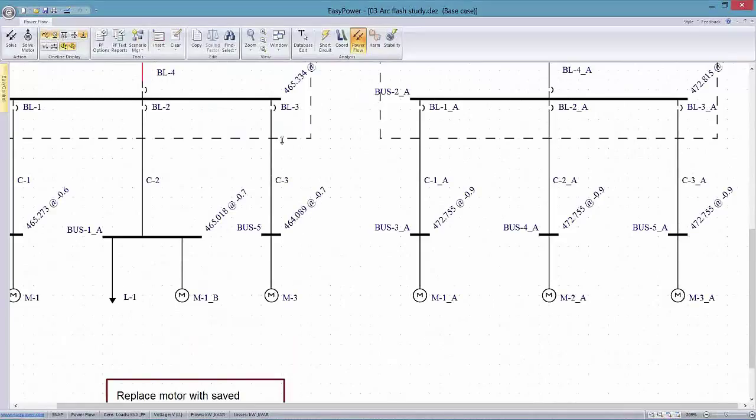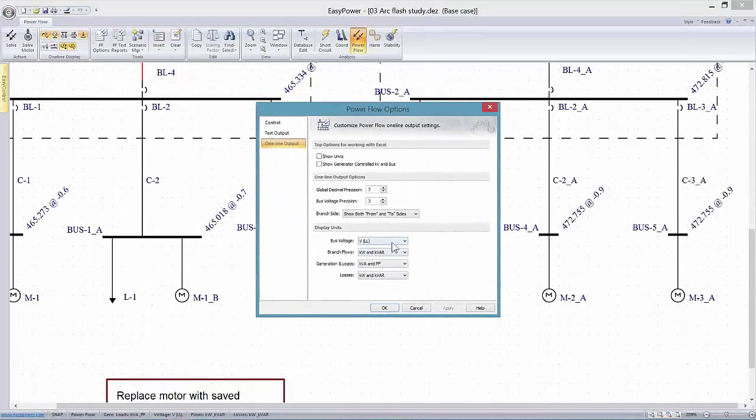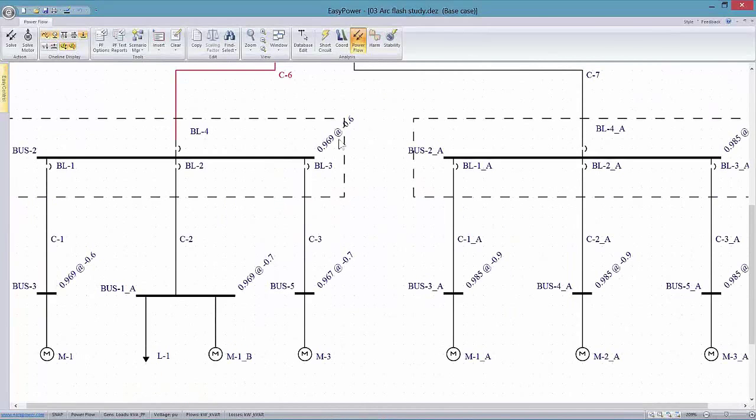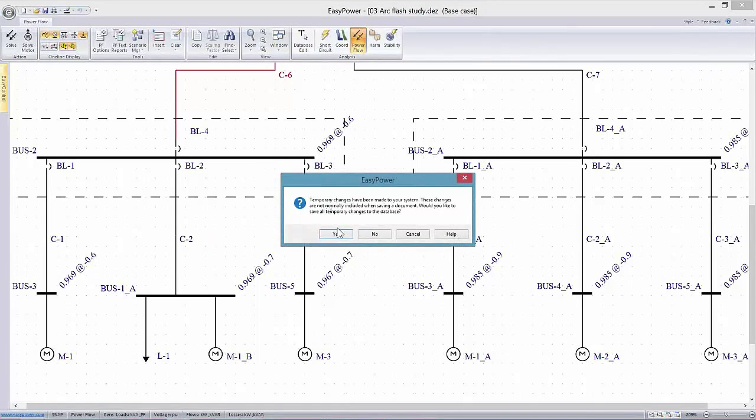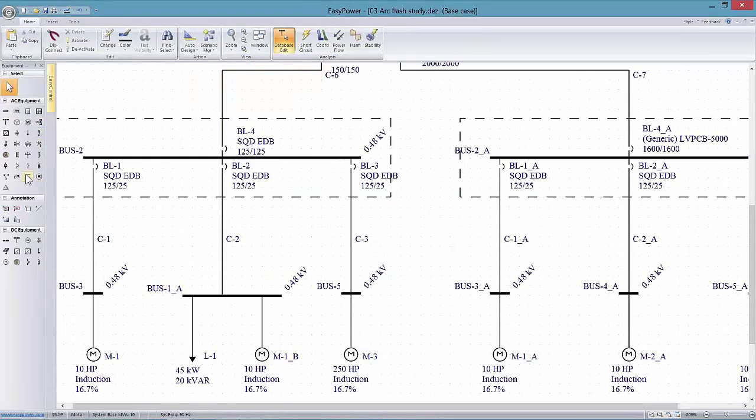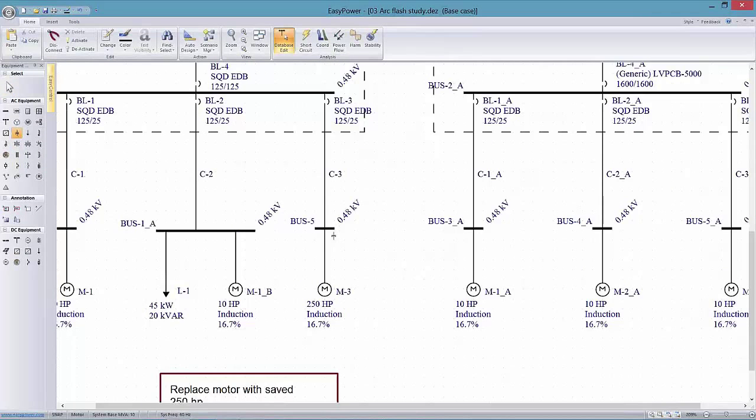So in the case of, let's look at our bus units. All right, so here we've had the bus voltage pulled down because of the load on the system. And if we take the load off, and this is a very large motor, we can see that the voltage on the bus goes up considerably. So one way to kind of deal with that, and again, this is not the way the designer necessarily goes about things, is to see what the advantage of adding a capacitive element into the system.